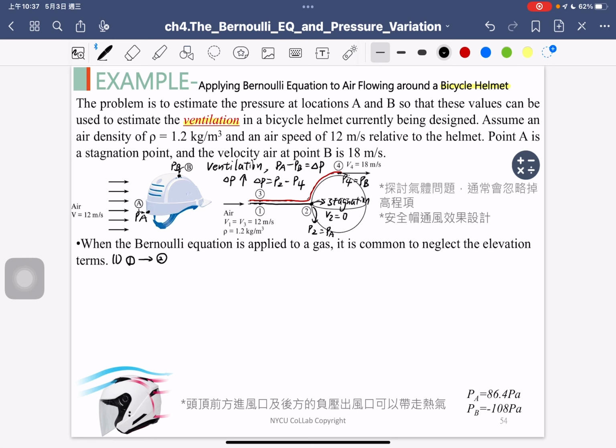Okay? Because this is along the same straight line, you can write down the Bernoulli equation very quickly: P1 + γZ1 + (1/2)ρV1² = P2 + γZ2 + (1/2)ρV2². Okay, and right now you can consider the items you want and you have.